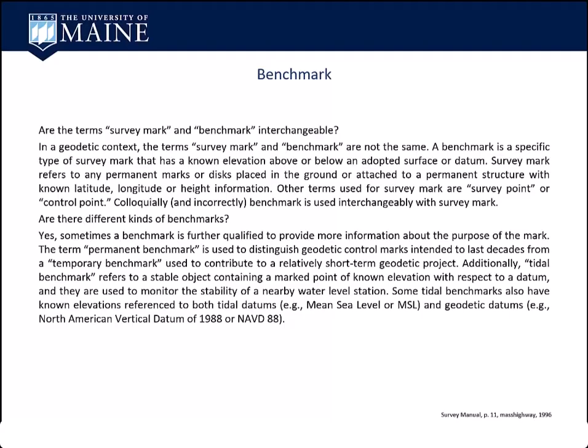A lot of times things are in 3D. That's fine, but when we're leveling, it's vertical only. Again, it says permanent benchmark, geodetic control intended to last decades, TBMs, short-lived. There are also tidal benchmarks that are tied into the tide cycle, I think 18.5 years, 18.6 years tide cycle.